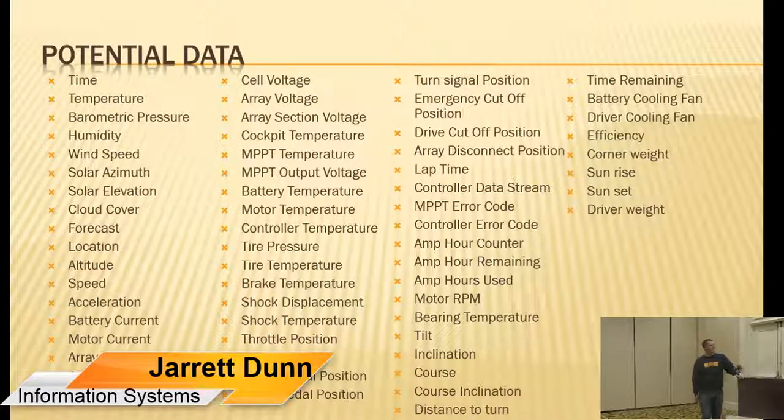I mean, even things like if you're trying to model your car, things like the driver weight, your corner weights. You might want to know your motor controller temperature. Motor controllers tend to become less efficient as they get hot. So there are all kinds of things that you could possibly use, but everything has a cost. In order to measure all these, it would be insanely expensive and require lots of effort and system. So you probably want to pare it down to what's important to you.